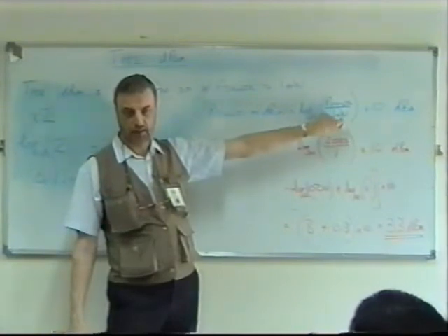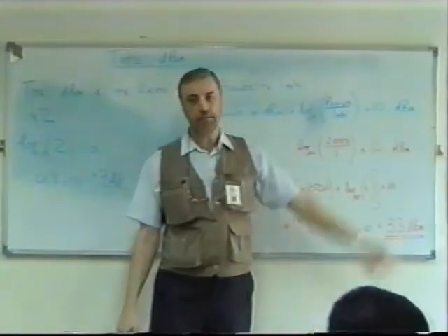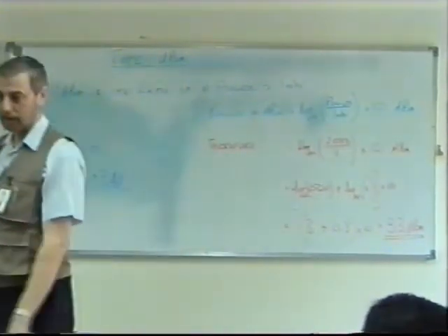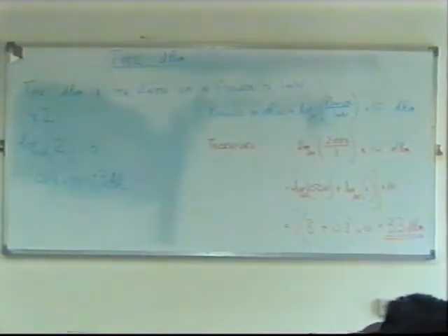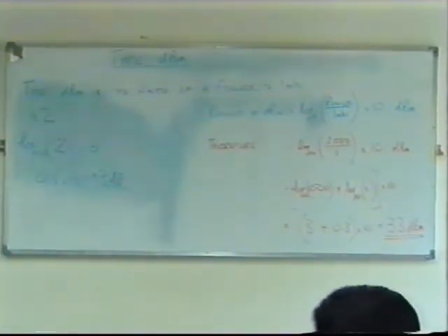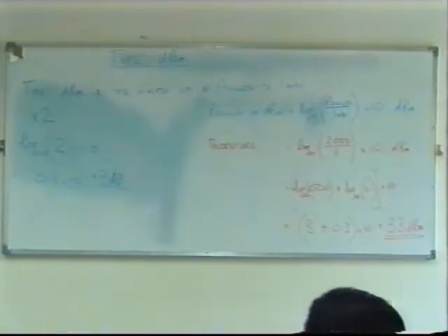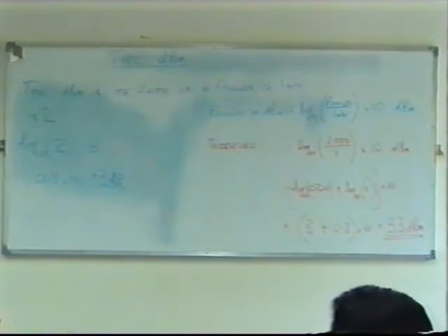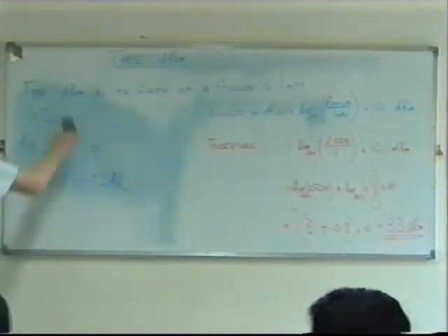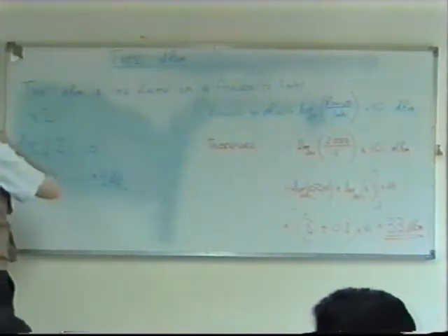That's fixed. So therefore we can say dBm is a measure of absolute power. Usually small power, yes. If you're talking about a 10 kilowatt transmitter, you wouldn't express that in dBm, it would be just too big. But for small powers, like the power output of a modem going onto a telephone line, or the power input to a receiver, because we're dealing with very small power levels there. Okay.